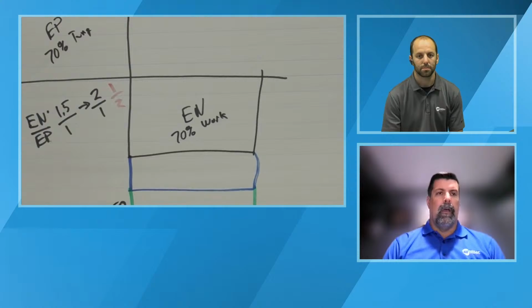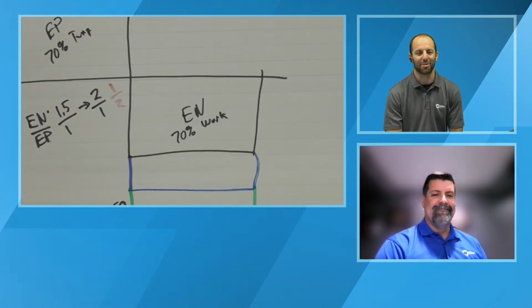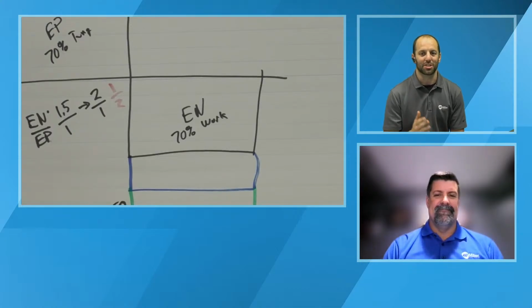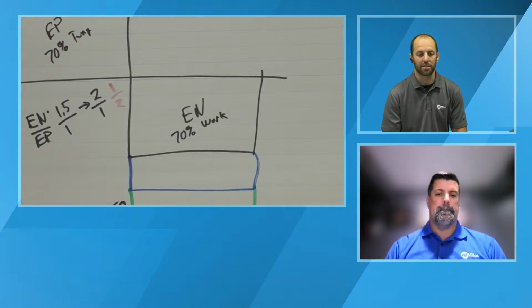Okay. One other point that I can't really stress enough: use the 2% ceriated or the 2% lanthanated tungsten. If you're using a pure tungsten, generally we know that those don't work well on inverter-based power sources. They can't transfer the electrons fast enough for the switching and the AC frequencies that we're doing with these products.